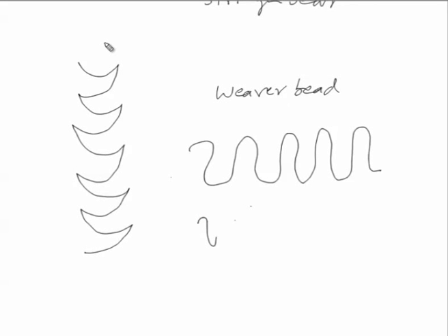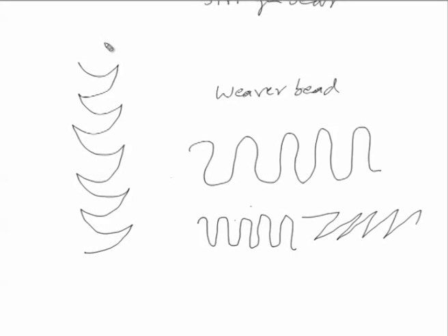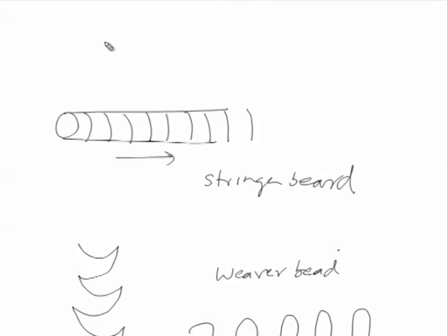And there can be different pitches and widths which can be covered during the welding, like this also can be used. So, when the arc is moved in different ways to deposit the weld metal using different patterns, the weld metal is not deposited in a straight line, but the arc is moved in zigzag, curved and irregular paths to deposit the weld metal. And there are different situations when these two types of beads are used.